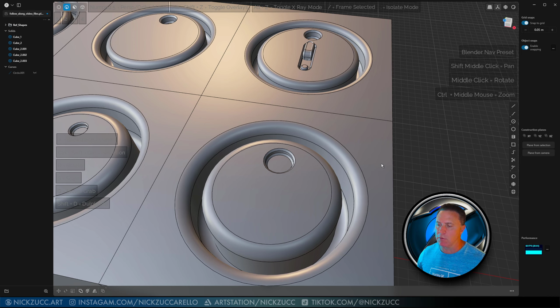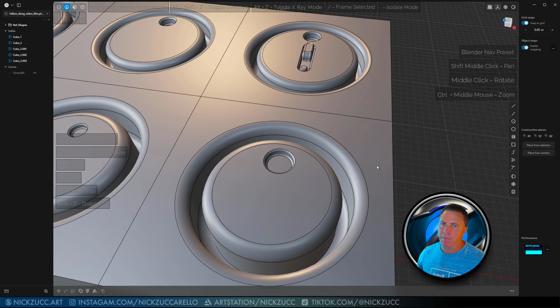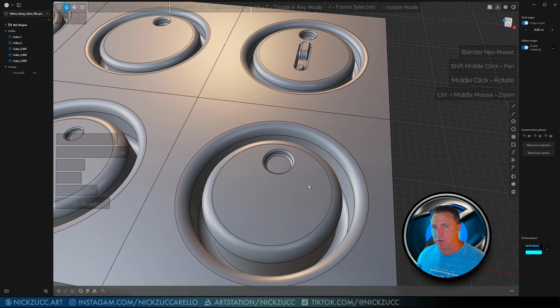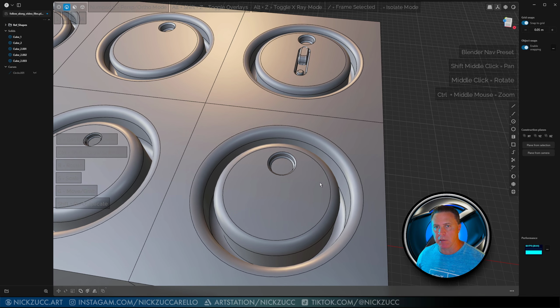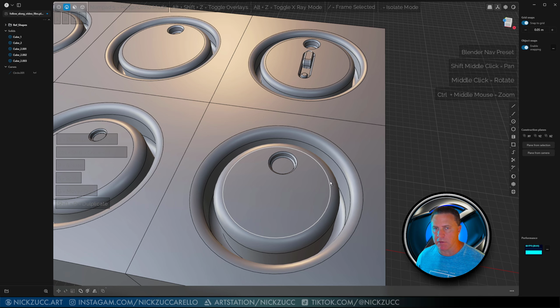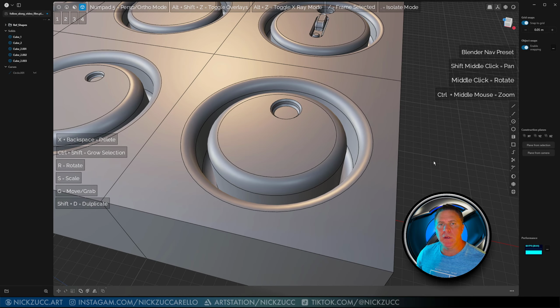If you are getting trouble with the fillets and the chamfers that you made, you might want to delete those first and get rid of them. And then you can move some of the features around. That's a little bit closer to what you're probably used to with polygon modeling, but that's how you get it done within Plasticity.